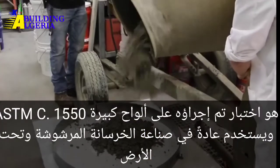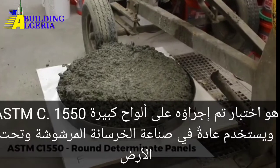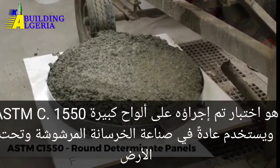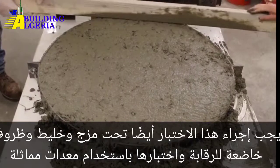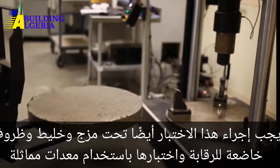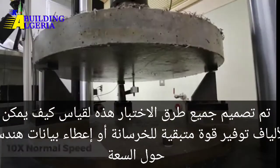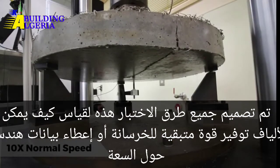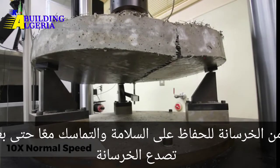ASTM C1550 is a test conducted on large panels and typically used in the shotcrete and underground industry. This test must also be performed under controlled mixing and placing conditions and tested using similar equipment. All of these test methods are designed to measure how fibers can provide residual strength to concrete or give engineering data on the capacity of concrete to maintain integrity and hold together even after concrete is cracked.